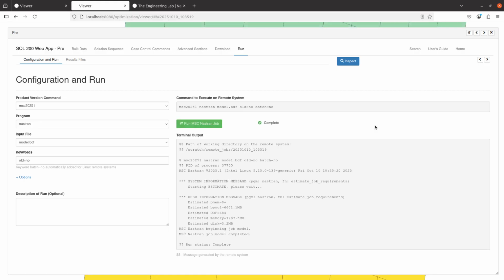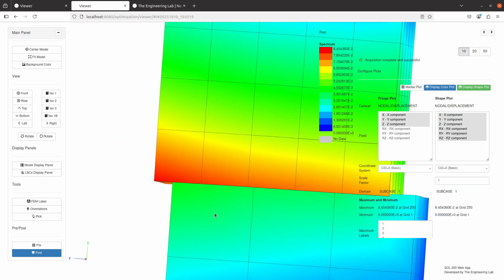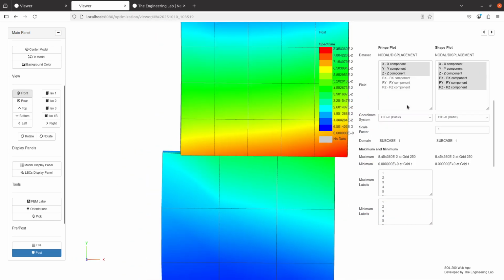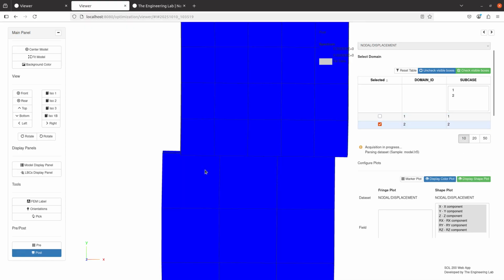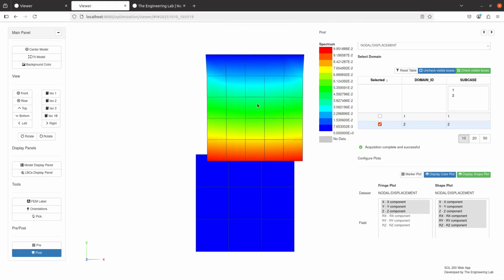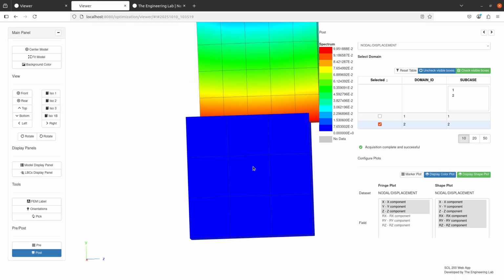And you notice that the face of the deformable body is smooth and in this case flat. So if we look at load case 2, which is not using contact, this is what that looks like. The top cube is going straight through the bottom cube, and you see the bottom cube is not even deforming.